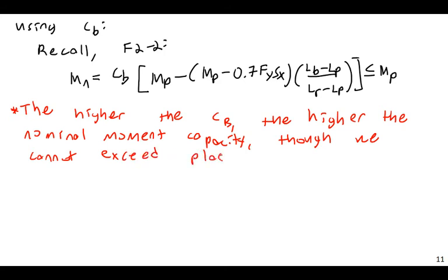The plastic moment capacity MP. We can't exceed that value. But again, the higher this is, the better. The lower it is, the worse. However, the nice thing about this, though, is we do have a lower bound. And because of that, we can often make a conservative assumption.